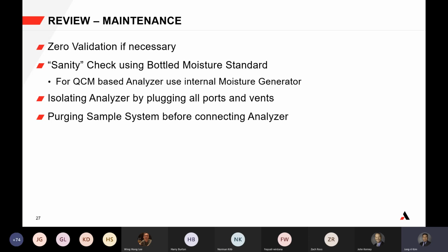And when you have that and you still have low readings, test it again the next day and see if you have consistent readings. If you have consistent readings from the bottle, that shows the bottle itself is outputting that. But whether it is actually 50 or not can be questionable. But it's a validation in the sense that your analyzer is reading consistently.